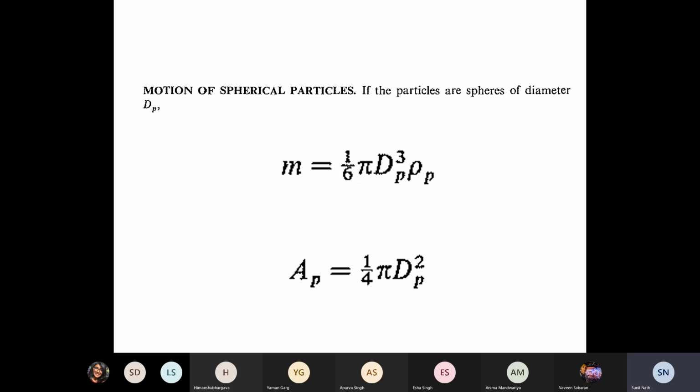And as you know from the viscous dissipation point of view, when the Reynolds number is low, the drag force is far, far higher. And it shows this logarithmic dependence that you just now saw with the 1 by Re dependence at very low creeping flow regimes.